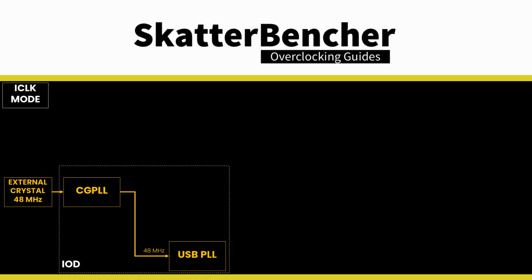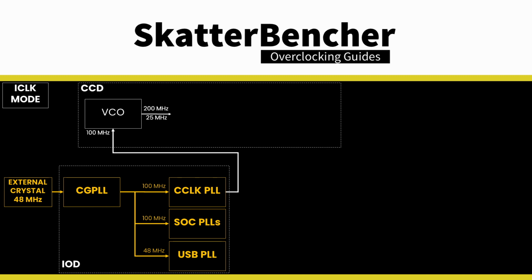The CGPLL then generates a 48 MHz clock for the USB PLL and a 100 MHz reference clock for the ECLK PLL for the CPU cores and several SoC PLLs. The ECLK PLL 100 MHz reference clock drives the 200 MHz VCO, which is then multiplied by an FID and divided by a DID. As a whole, this provides CPU clock frequency granularity of 25 MHz.